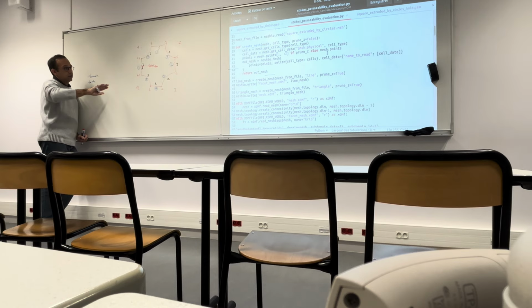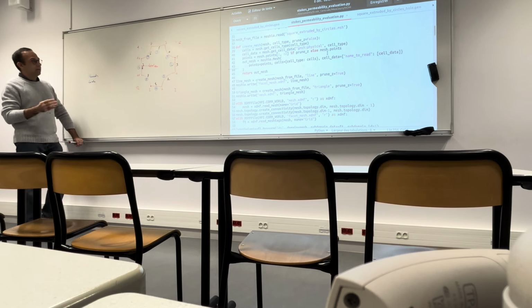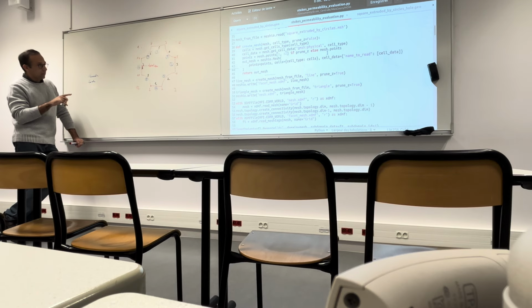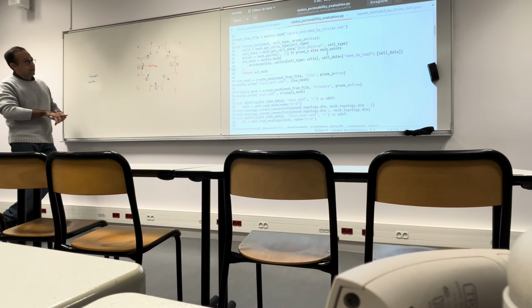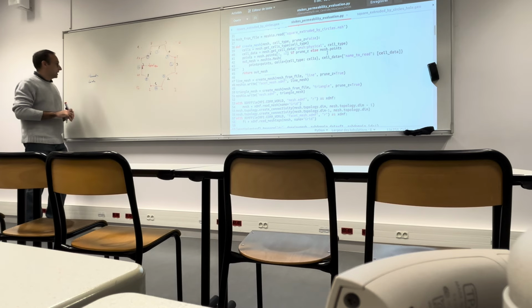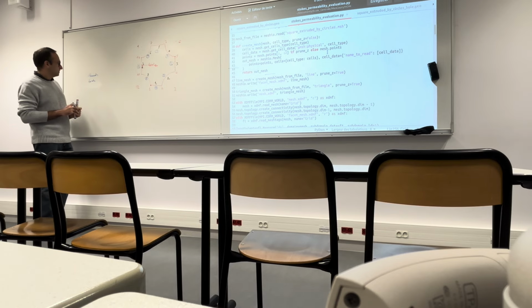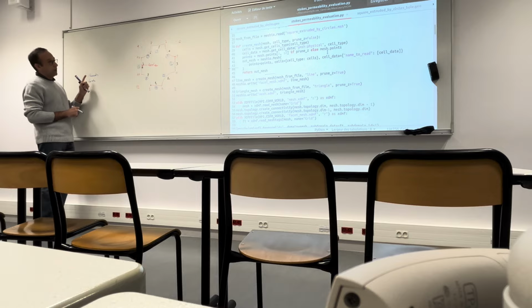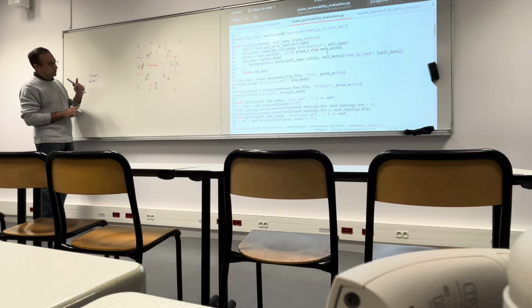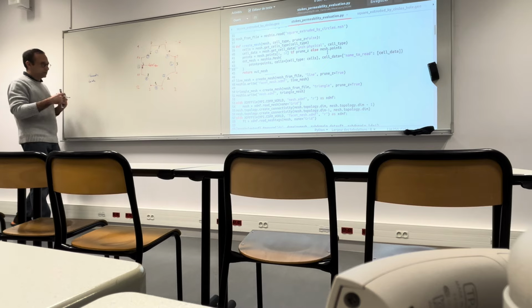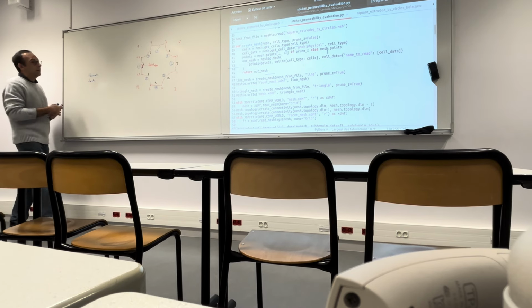Facets are just the boundaries of every element, which also identify the lines through which the couple of elements are in contact. And this is in particular important when we want to specify boundary conditions, because we need to specify boundary conditions on the nodes which are on the facets staying on the boundary. So this is a little bit tricky, but this is clear.